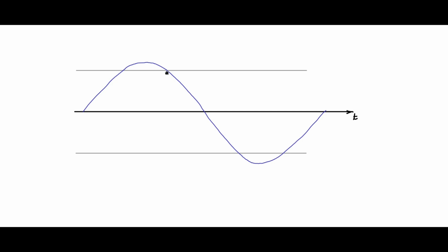Now what we can do is, let us say I have this third harmonic. This is the third harmonic, the triplen, and I will use this. I will subtract this from this. If a triplen is injected in a three-phase system, it is not going to affect anything because it is not providing a rotating phasor.